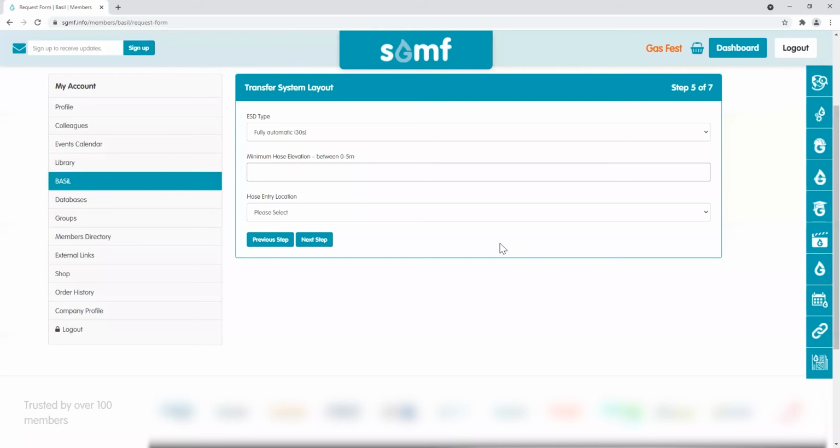So what we really want to do is get the hose a little bit off the ground to get mixing underneath. Effects start at about 0.3 meters, 30 centimeters and more, and the effect runs out. So anything over 5 meters really doesn't matter. I'm going to put in 0.3 meters there. So I'm going to have my hose a minimum distance off the deck.